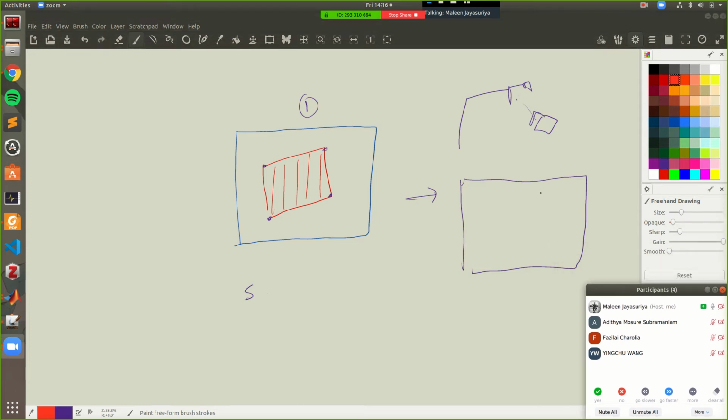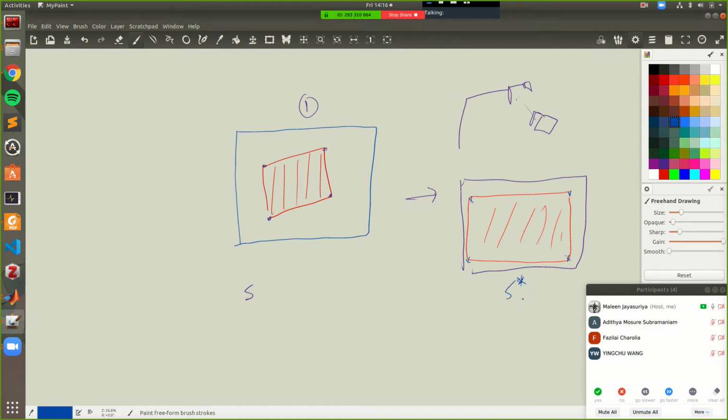When it comes closer, maybe the cube has to align like this nicely in the image and become larger. And so we have an idea of where the pixel values should end up. That is what we call S star. S star is essentially that reference value that we have in our control system. This is where we want our features to end up.